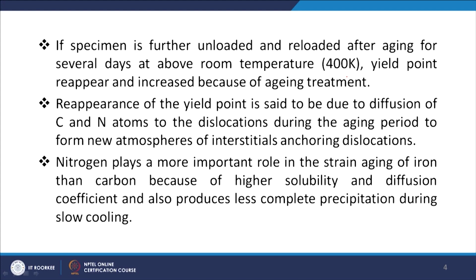So basically it is very important to avoid this strain aging, especially when you go for phenomena like deep drawing. In those cases, if there is reappearance of the yield point, that may lead to improper surface finish, because it may lead to marks on the product. These marks are known as stretcher strains. So normally we try to avoid this.